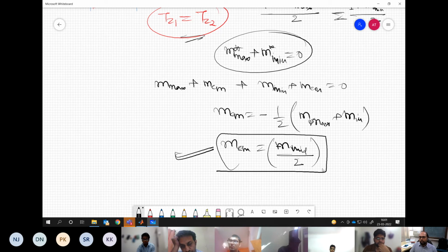So this is our common mode which we see in the equivalent of space vector PWM. If you want to implement that, which is your next exercise in the lab, this is the common mode which you need to add.